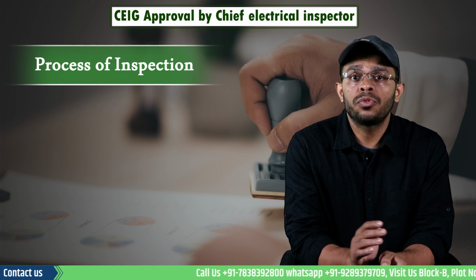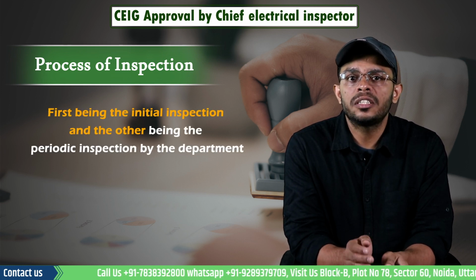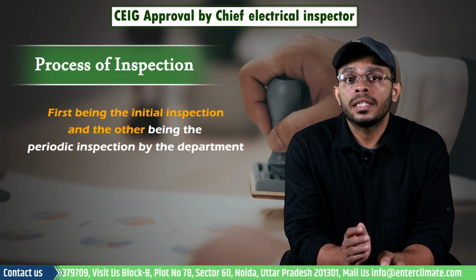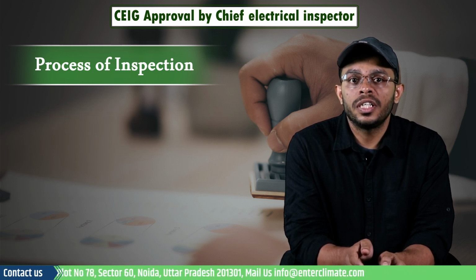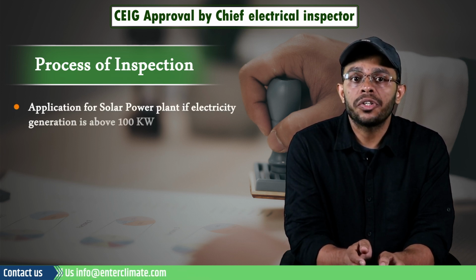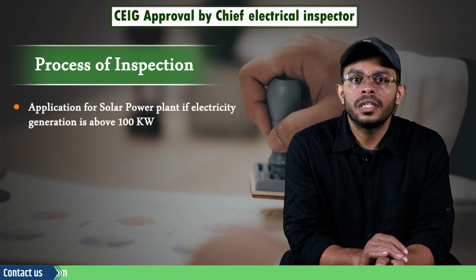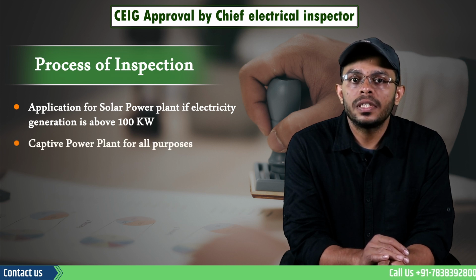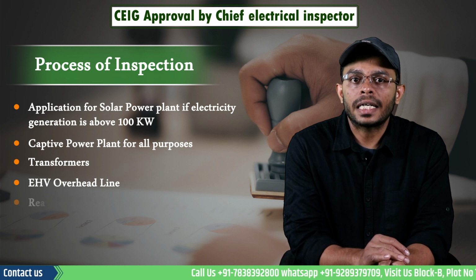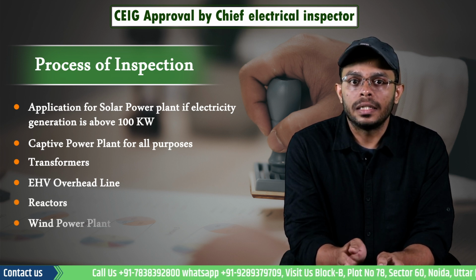The inspection is of two types, the first being the initial inspection and the other is periodic inspection. The cases in which the certification of electrical installation by the Chief Electrical Inspector is required are application for solar power plant generation, captive power plants for all purposes, transformers, EHV overhead lines, reactors and wind power plants.